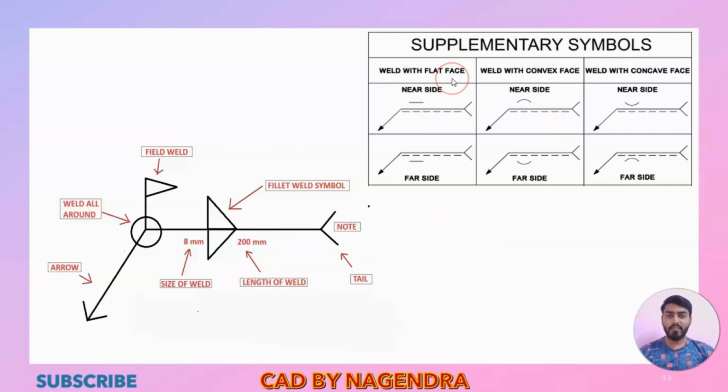So, weld with a flat face. Let's say for example we are having two flat faces like this. Then either welding should be done upside or downside. We need to mention it with this. So near side means welding should be done here on the upside. Far side means welding should be done on the downside.